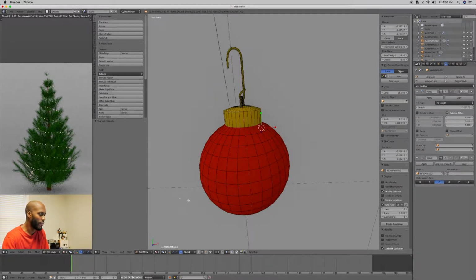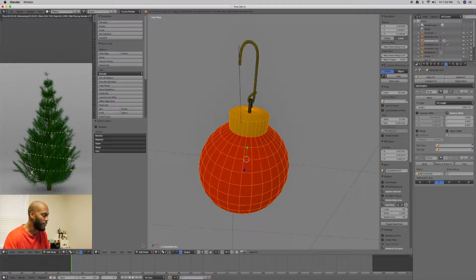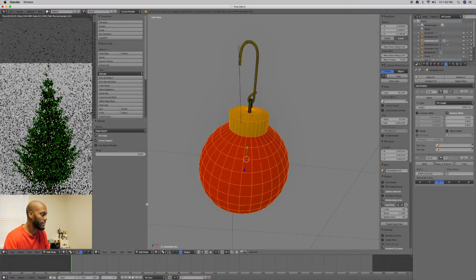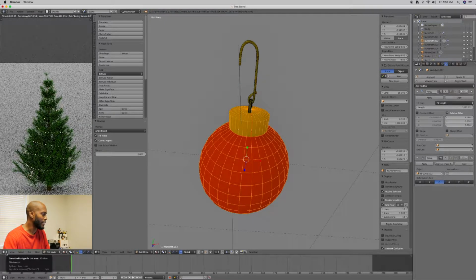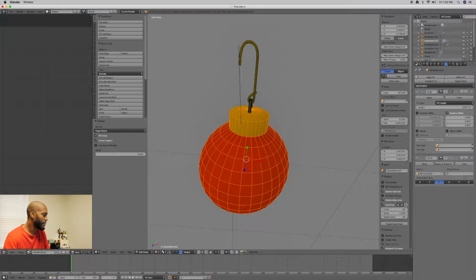and that is better shown off when we grab our object, push L for link, so we're grabbing everything and all the objects that have been marked with a seam, and we're just going to UV unwrap it. So mesh, UV unwrap. And we're going to go ahead and take a look at what that looks like. So in our render viewer over here, we're just going to go to UV and image editor. Click on the results here, and then it'll show you our results for when we UV unwrapped it.